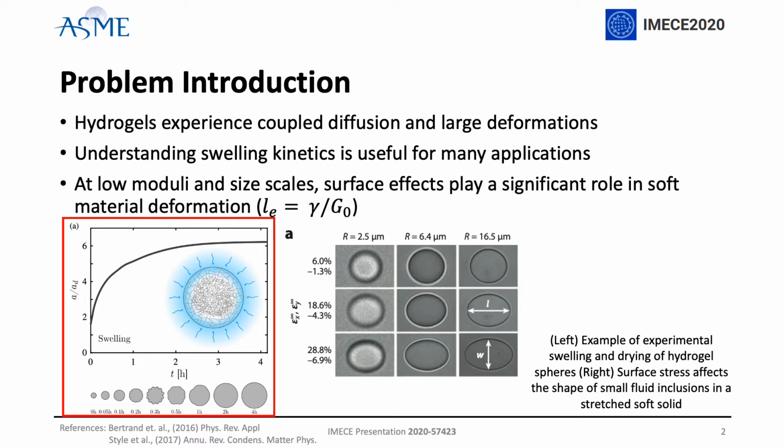Understanding these time-dependent kinetics is important when fabricating micro or nanoparticles which will release a drug agent of interest during the swelling process. The novelty of this work lies in the consideration of surface stresses which can significantly influence soft materials at sub-millimeter length scales and at low moduli.